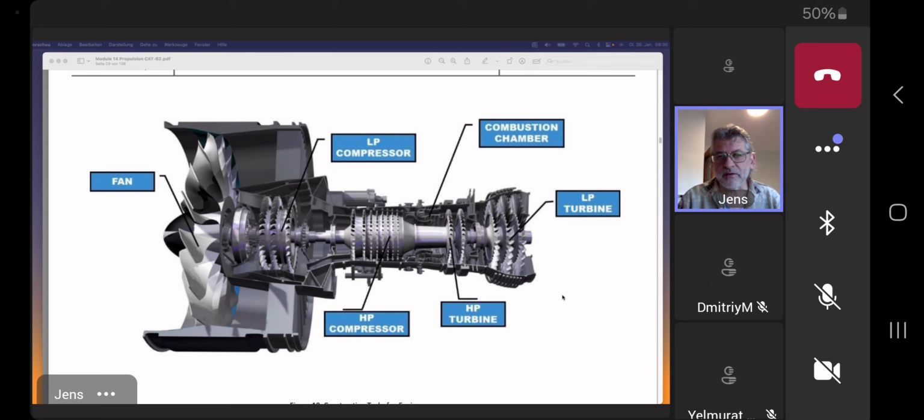Unfortunately, you're not able to travel at a very high altitude, but in general, due to the low weight and the low fuel consumption, the engine has an advantage. Please bear this in mind. And also, since the gas turbines of turboprop engines are mainly free gas turbines, they can turn at their optimum RPMs, so the time between overhaul is also much longer than normal gas turbine engines.